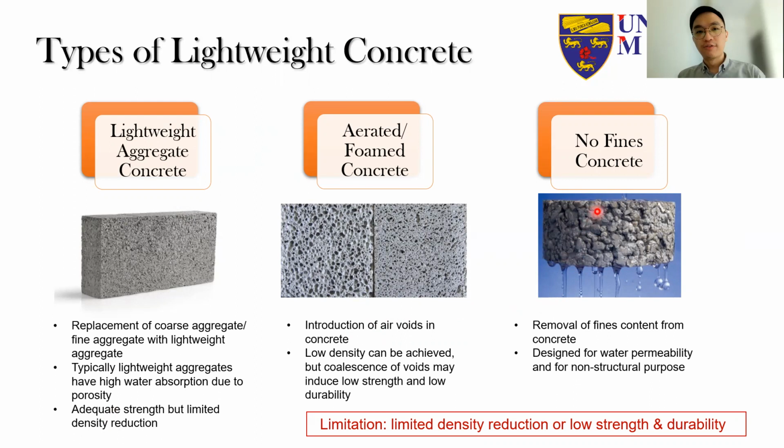So a third type of lightweight concrete is the no-fines concrete, or we also call this pervious concrete. This typically involves taking out the fine aggregate portion of the concrete. Usually this is only designed for water permeability and also for non-structural purposes.